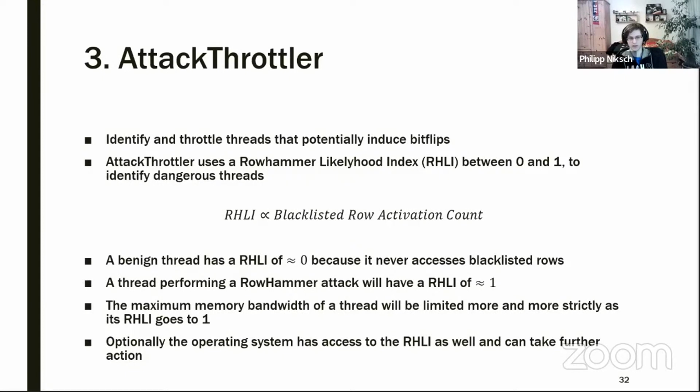But this will not allow you to get a RowHammer attack working, because RowBlocker itself is enough to mitigate an attack, but you could get around AttackThrottler in that way. So your memory bandwidth does not get decreased. Right, because as soon as a row is blacklisted, it's basically safe. Yeah, okay, thank you.